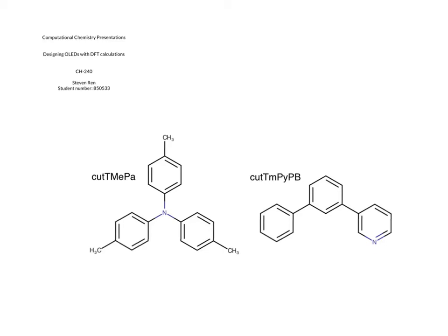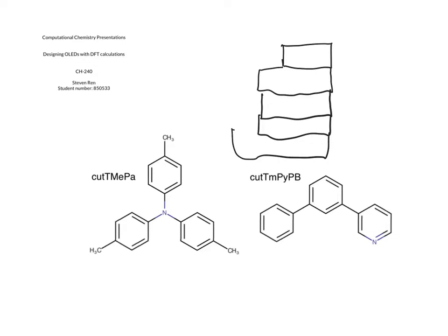Well, there are two main classes of organic light emitting diodes: OLEDs, so-called small molecule based light emitting diodes, and PLEDs, so-called polymer light emitting diodes. A typical double heterostructure small molecule OLED consists of three organic layers sandwiched just like this.